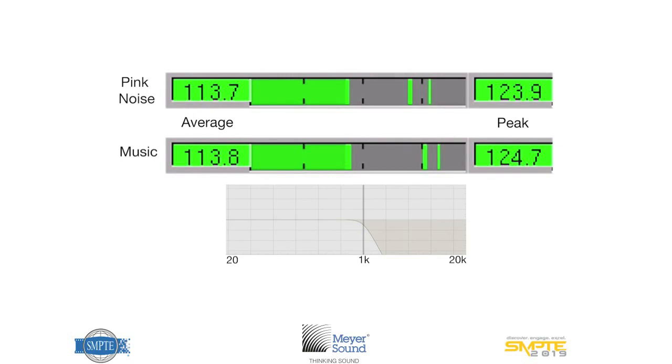It doesn't even tell you if you can get to 86. So that's what we're after. With this sensitivity, a certain dBFS is supposed to produce a certain dB SPL. Well, it's pretty easy to calculate what SPL full scale digital should produce. So I have an analysis that I'll show in a bit.